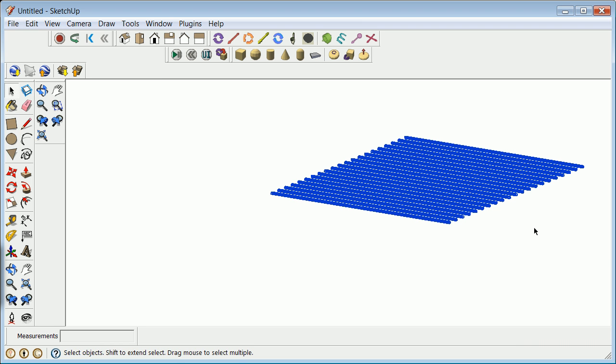Okay, why we're making it into groups is later on we'll be able to move those groups up or down based on changes in what's below it. Top down, bottom up. If all of a sudden, you do need to keep track of these levels and elevations. In this case, you're doing it by using a group. In Revit, you'll be doing it by using levels.